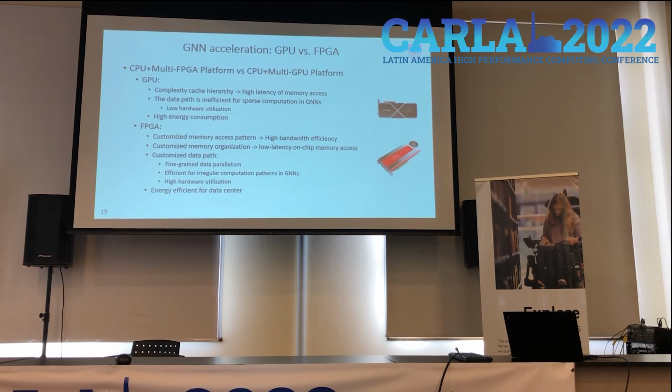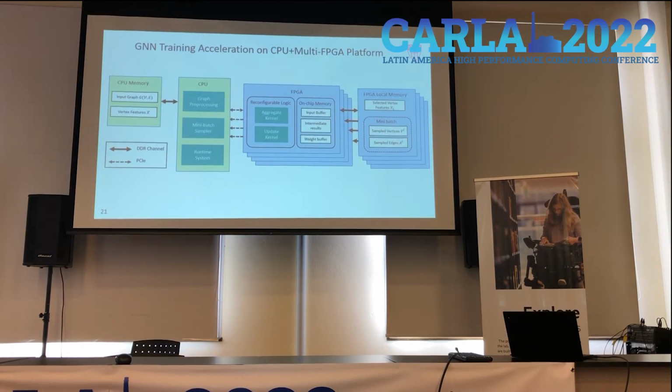In all of these FPGA devices, you define this data path. You structure this, and use the high-level synthesis tools to generate those data paths. That gives us a very nice way by which, based on the particular GNN model computations you are doing, we can implement those aggregate functions very efficiently on the FPGAs, which gives very high performance in our implementations.